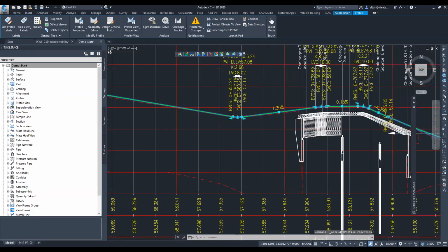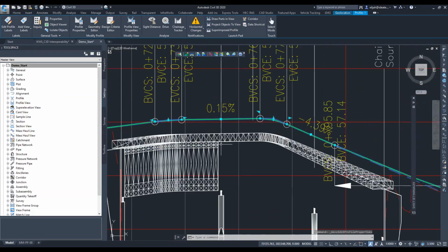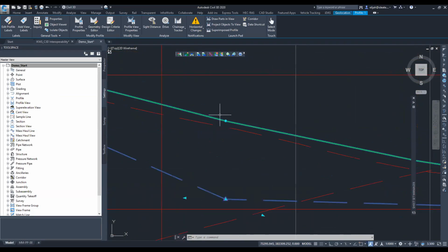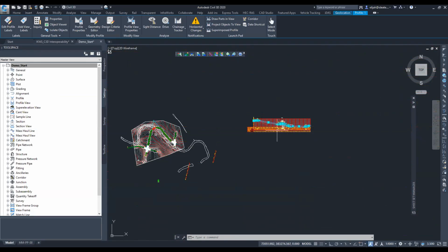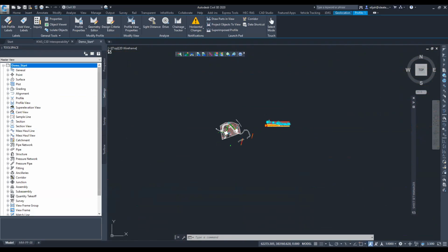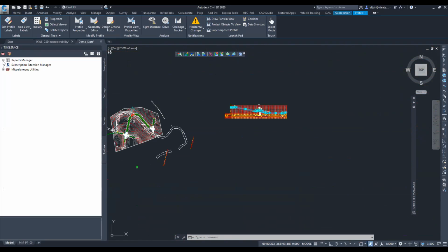So if I go again now, you'll be able to see if there are any points along the curve which are violating the design speed. Again, I should be able to see a warning symbol, of which there is none, because I already adjusted them accordingly. After that, we'll be able to produce the report. If I want to produce that design verification criteria for my vertical curves, I'll go into the toolbox and generate the results in terms of how it ensures that each of those parameters is met. If the passing sight distance is this value and the stopping sight distance is this value, what does the code specify and what have I specified in my design?